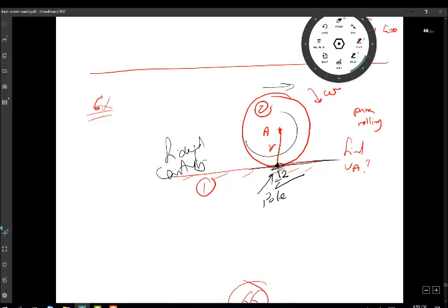And the moving centroid is the wheel itself, because as it shifts to another point, the point that was in contact before remains on the wheel and becomes a point on the circumference. So the wheel itself is the moving centroid and the ground is the fixed centroid, if you want to think about it in terms of centroids as we did last time.